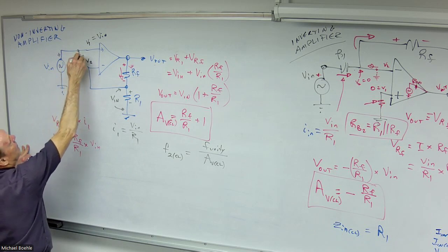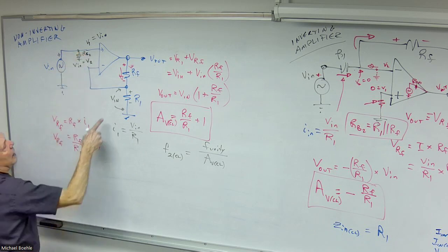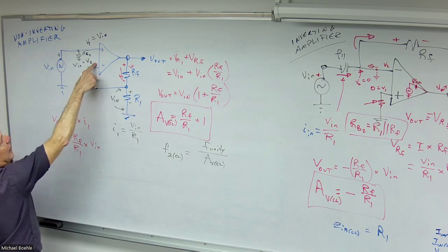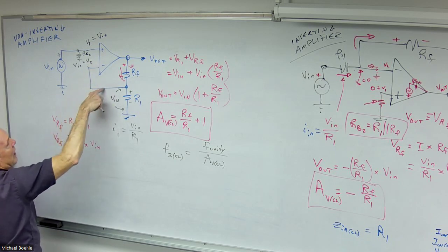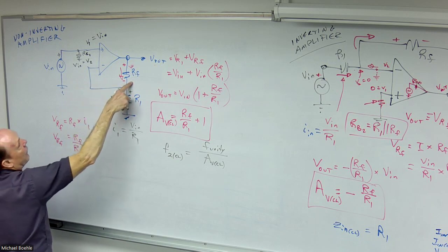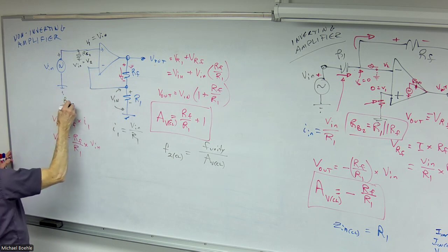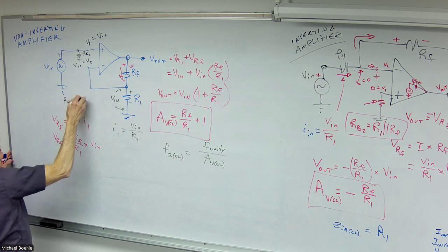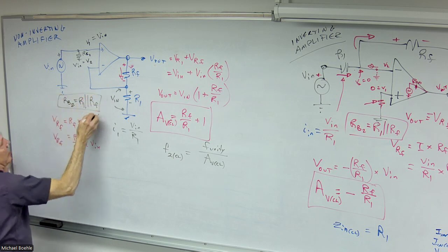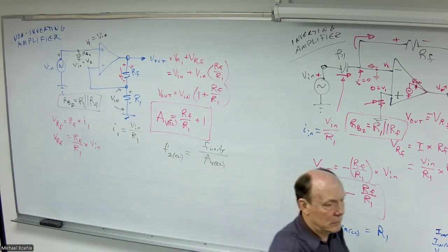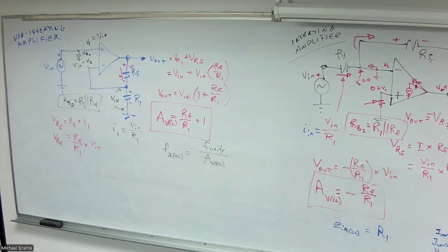If I put in my matching base resistor, call that RB2, from the perspective of the other base, again, looking back out, I see R1 to ground, the feedback resistor back through here to ground. And so RB2 would again be R1 parallel with the feedback. Non-inverting amp.